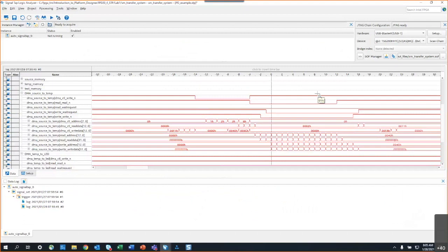So this user says, I am using a FIFO to get data from an ADC running at 125 megasamples per second, going into another clock domain running at 250 megahertz. So basically crossing clock domains. The clock that he uses on SignalTap is the ADC clock.